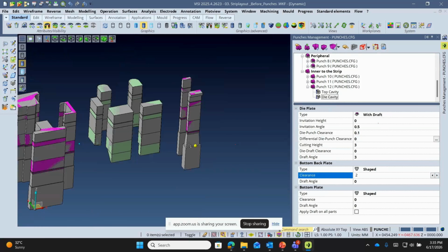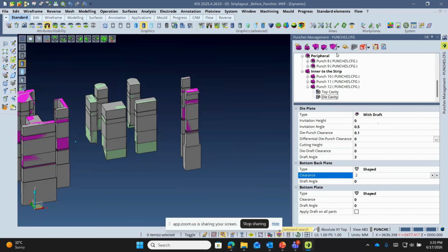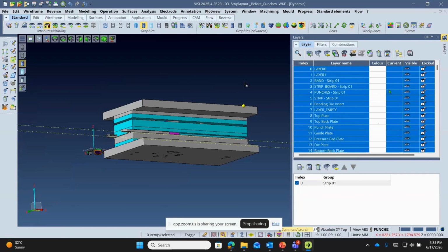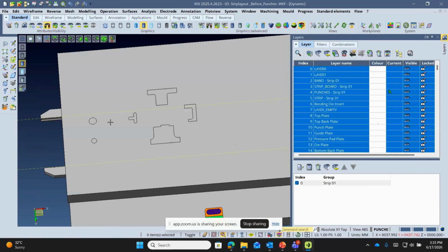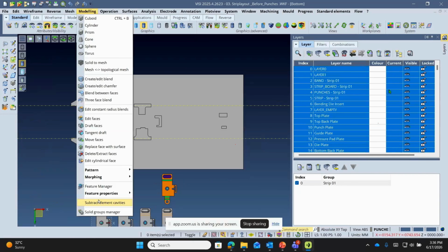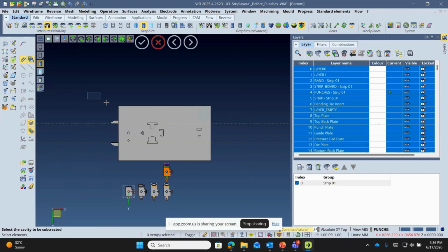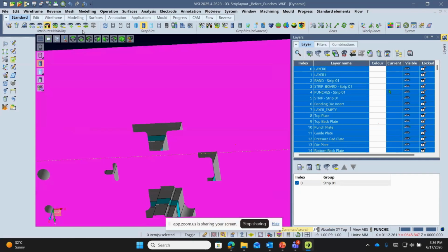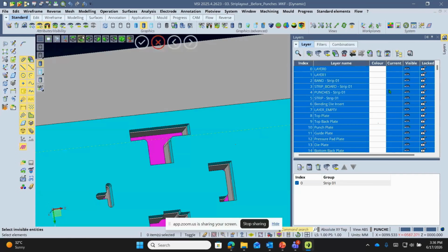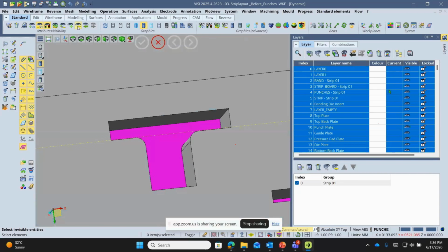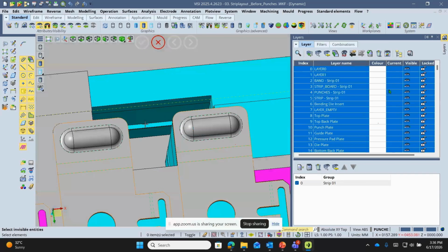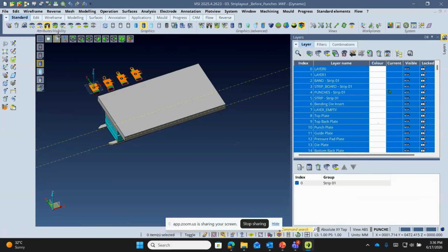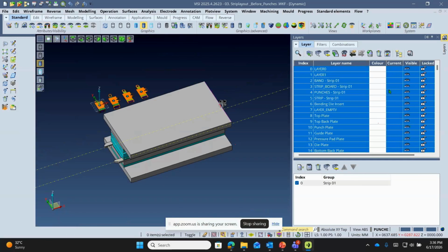Here multiple methods are available. You can use them and create the complete punch management. So once we create the punches, the remaining is the same. I will use the subtract element cavity. Here you can see it automatically generates the relay hole. Then you can see the punch profile also. If I change the punch profile, the entire parameter is updated automatically. So this is the punch method.